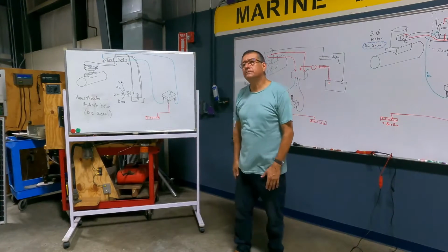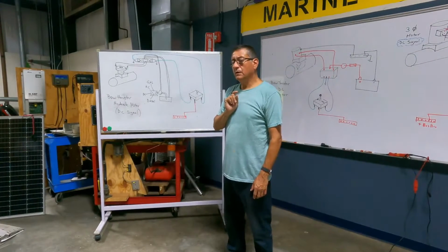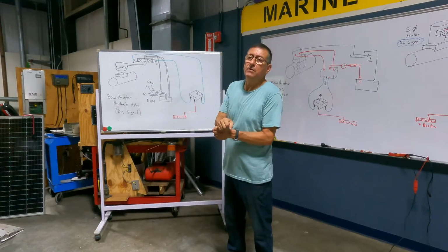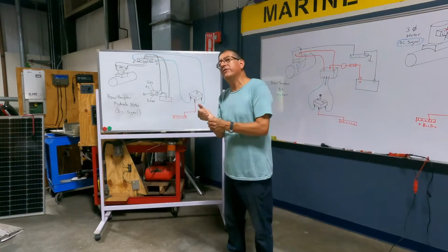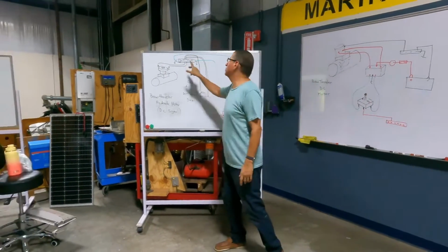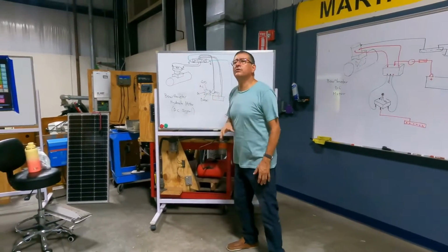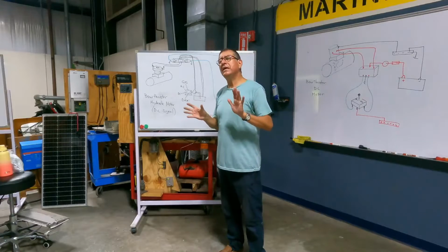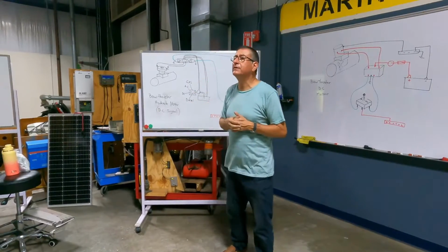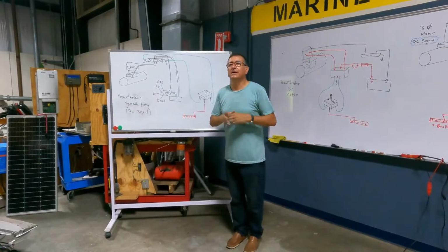Pay attention. The captain said that it's moving in left side, but it's not moving in right side. You check, everything is good. The solenoids are good, the cables are good, the joystick is good, the motor is good. What could be the problem in this particular case? Air in the system.